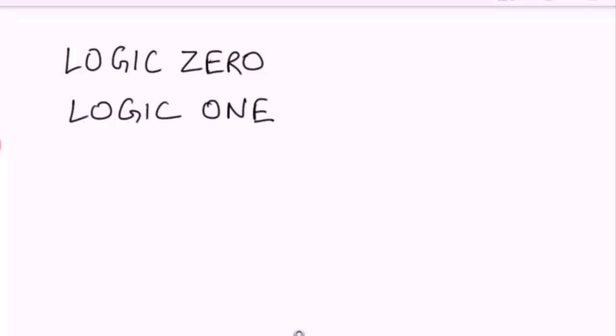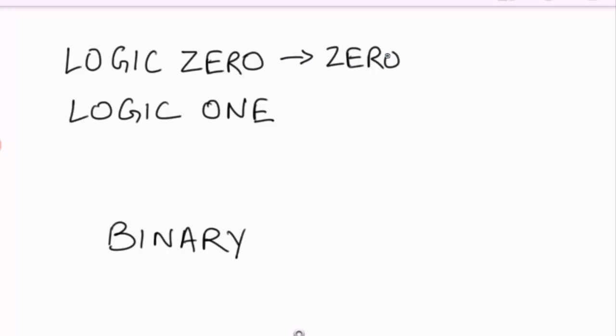If you are familiar with computer technologies, then you probably know that a computer always works in binary, which is 0 or 1. Similar is the case here. Our microcontroller works in binary. So here logic 0 means 0 volts, and logic 1 means 3 volts, because in this Discovery board our microcontroller is currently working on 3 volts. That means if we give 3 volts to the microcontroller, then logic 1 will be equal to 3 volts and logic 0 will be equal to 0 volts.